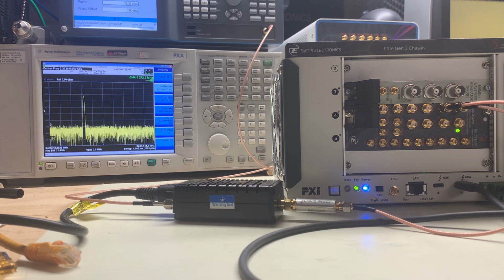This is a very slow linear frequency modulation, if you will, and I'm achieving it by downloading 10,000 points of waveform data to the instrument and then incrementing the frequency slightly on every download. So I'm using the real-time streaming capability of the instrument here, and every increment of stream I increment the carrier frequency.